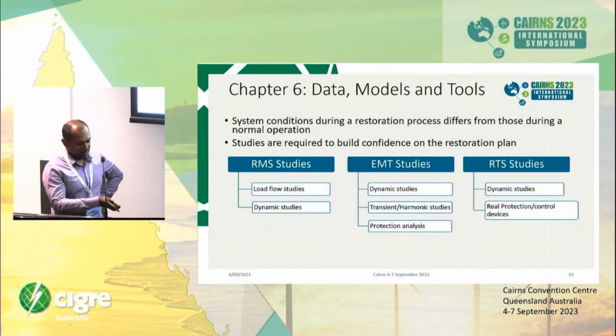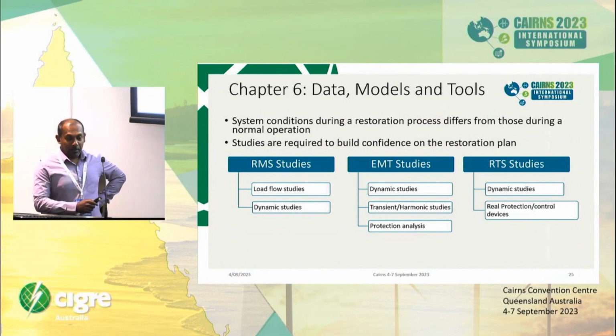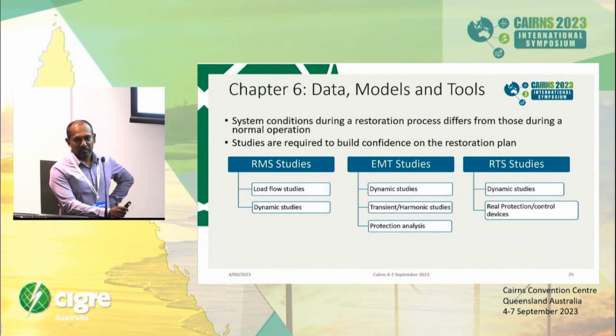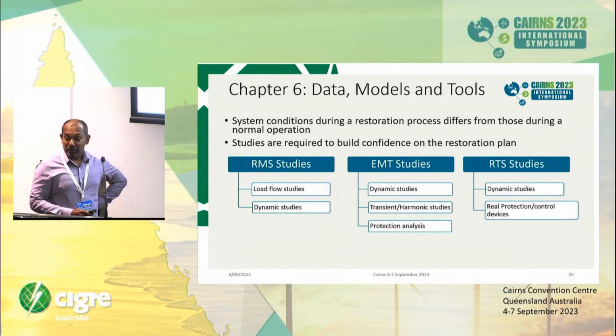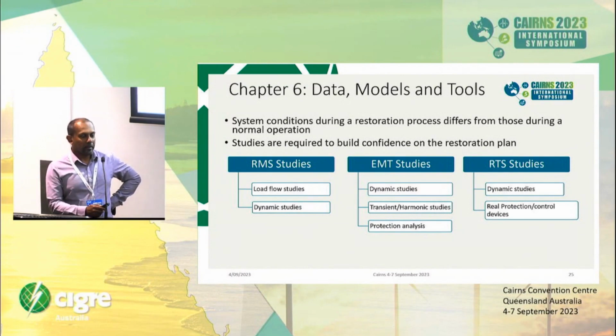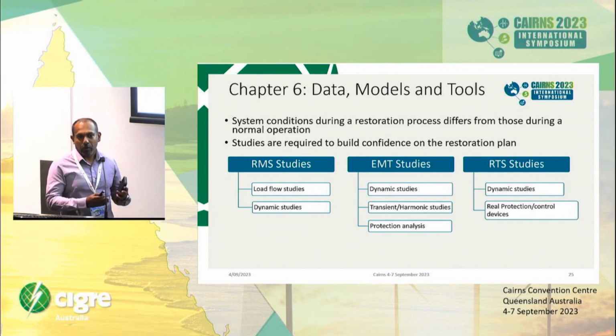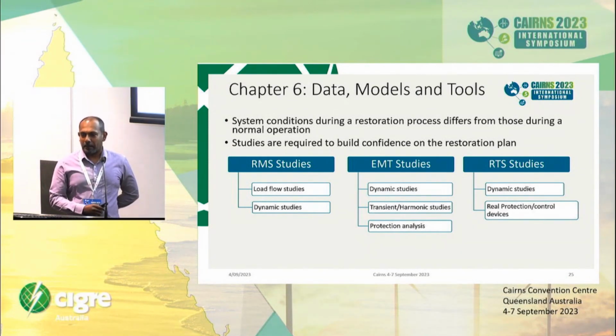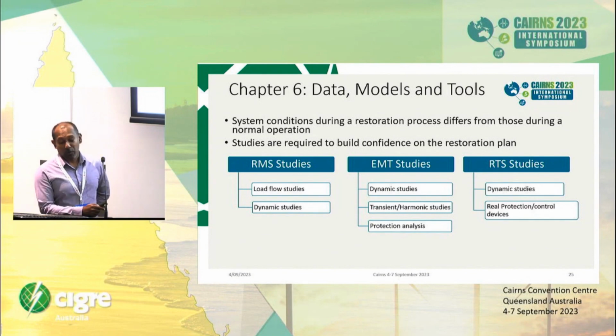Okay, yeah, thanks. Obviously, the black start situation is completely different from the normal system condition. Therefore, it is very important to do a study and build confidence about the restoration path. And if some mitigation options are required, you have to implement them, from a simulation point of view, and make some justification that the restoration process is secure. I'm mostly talking here about the general studies, the studies in all the general tools.